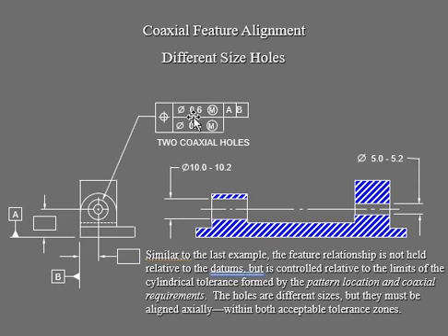So here, in this example, we have 0.6 and then 0.3: 0.6 for the pattern, and 0.3 for the position of that hole, and we are dealing with maximum material. We have two coaxial holes right there, one and then here. Of course, when you look at it in your right side view, you can see the cross sections of material right there.